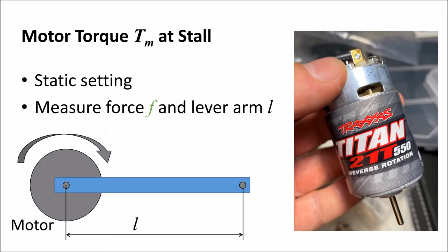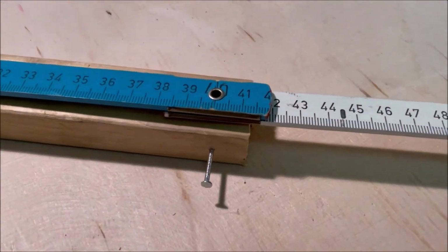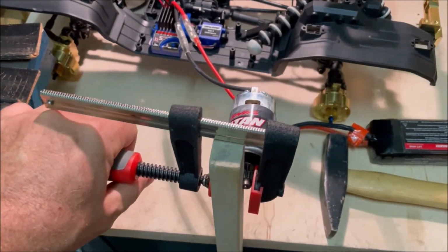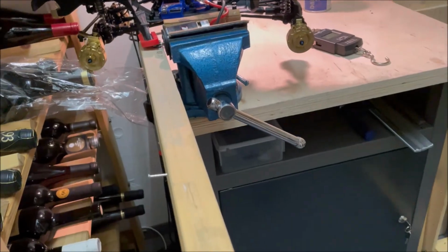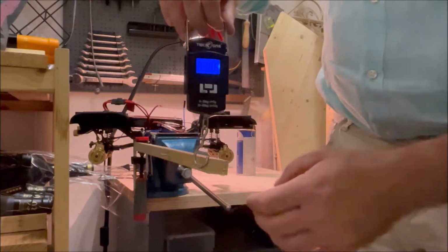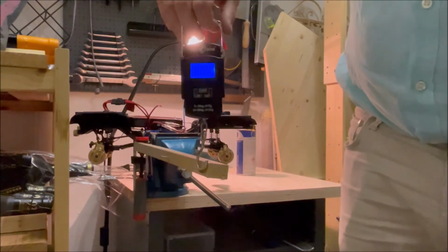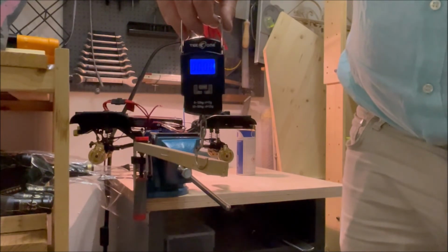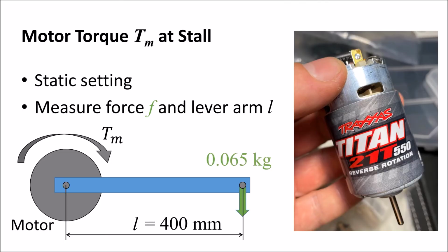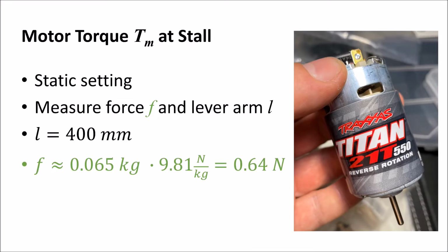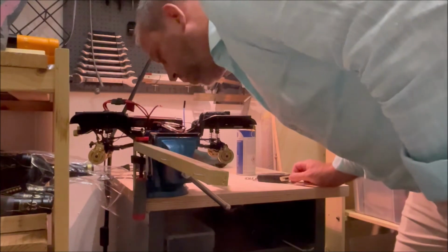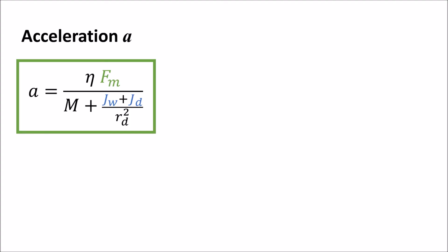The motor torque was experimentally determined only for the static case. This torque is called stall torque and it applies only for zero or very small rotational speeds. Attention! This test is not recommended because the motor gets really hot due to the missing cooling in that static condition.